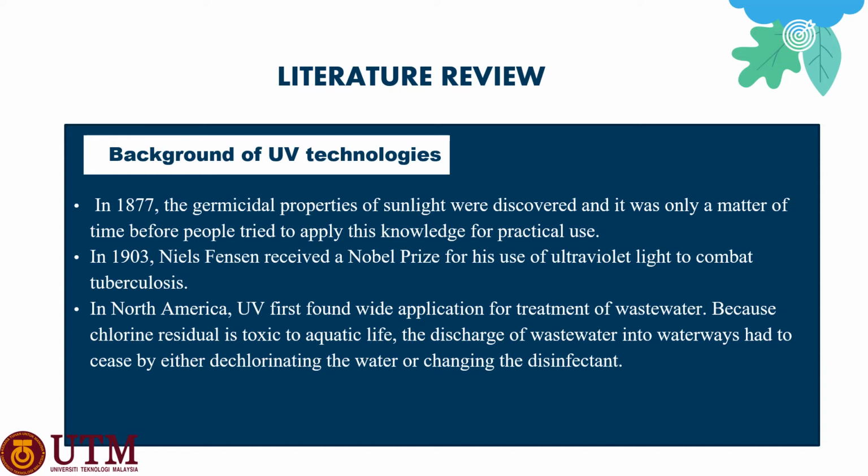For example, in North America, UV first found wide application for treatment of wastewater because chlorine residual is toxic to aquatic life. The discharge of wastewater into waterways had to cease unless either dechlorinating the water or changing the disinfectant. The use of UV disinfection for wastewater treatment has increased dramatically in the last few years due to the impact of chlorinated organics from sewage effluent on receiving water. In brief, about the background of UV technology, preferable for zero chemical residual, UV disinfection is the major option for water treatment over chlorination.